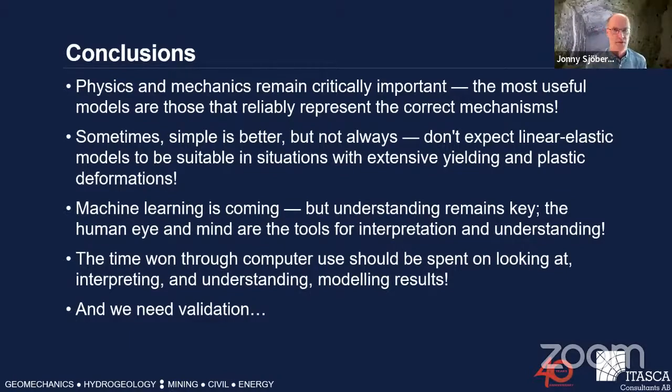Sometimes simple is better, but don't expect the linear elastic model to be suitable where you think there should be a lot of yielding and plastic deformation. Then you're just fooling yourself.